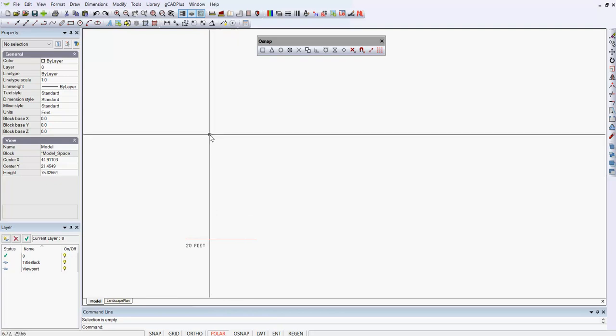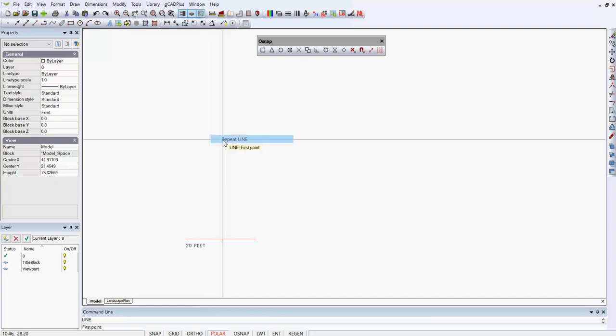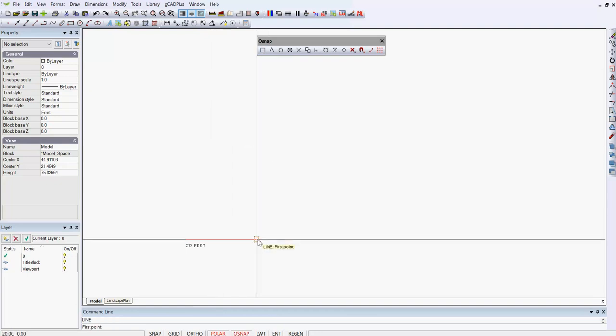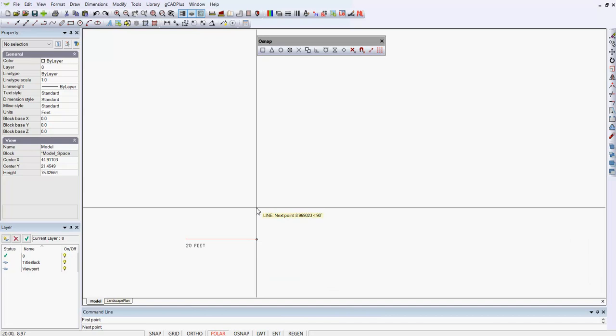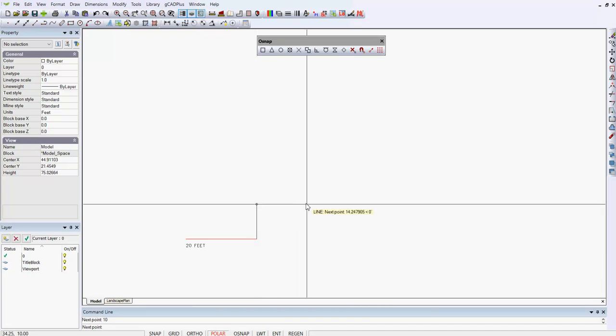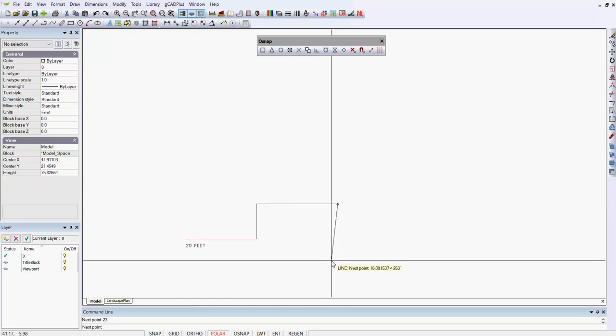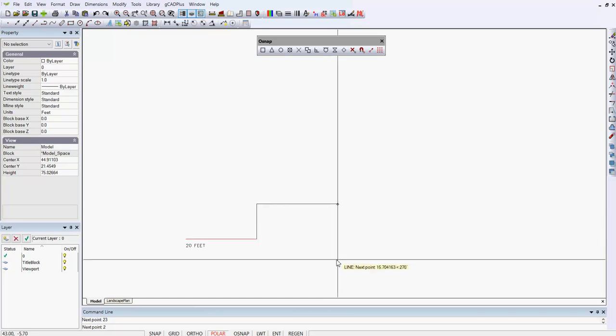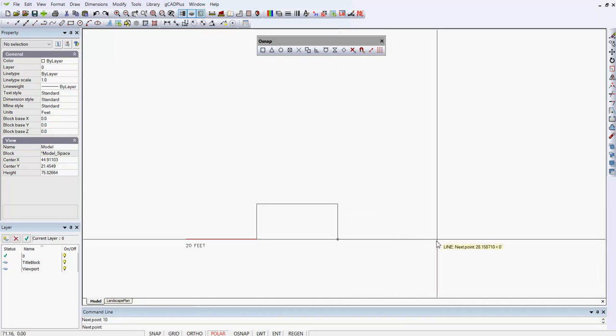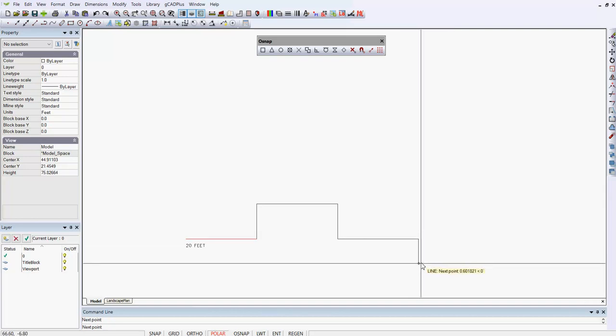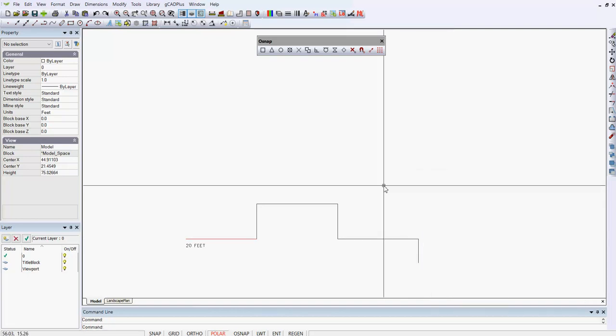So all the tools that you need to create your landscape plans are here. Let's right click and start the line again, and we'll start it at the end here. Let's imagine this is the footprint of the house, and we would go 10 feet in this direction, 23 feet, let's say, in that direction, down here 10 feet. Notice that I can pull down and just type 10, and the line goes in and pulls back. We might go over here some distance, say 23 feet there, and I won't put any distance on it, and I'll just click, right click, and exit.